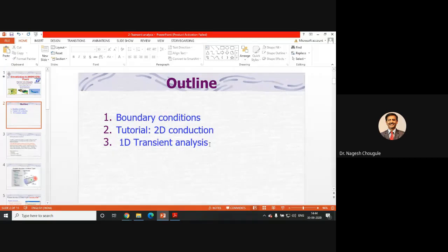This way, parameters can be imported from previous CAD software also, and you can define mesh size as a parameter too. In mesh independence analysis, what we normally do is go on changing the mesh size from coarser to finer with a certain step, and at every size I check the responses.